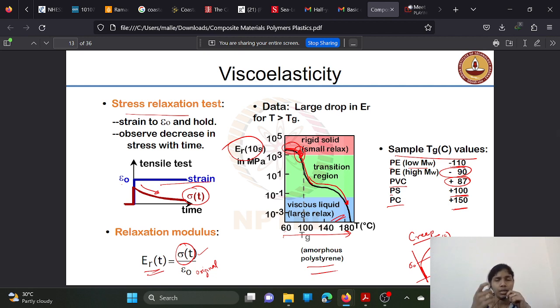Stress relaxation test is nothing but, for suppose if you take bitumen and if you elongate it in the longitudinal direction, and if the strain is maintained constant, then what will happen is the material will adjust the stress concentration within it, and it will get relaxed, like the stress relaxation test.